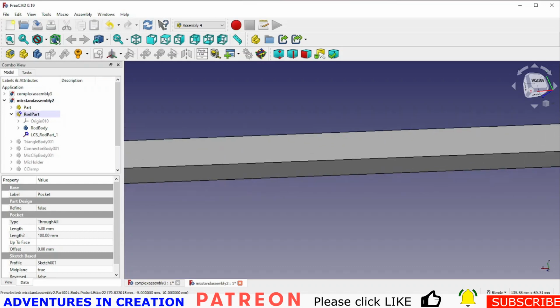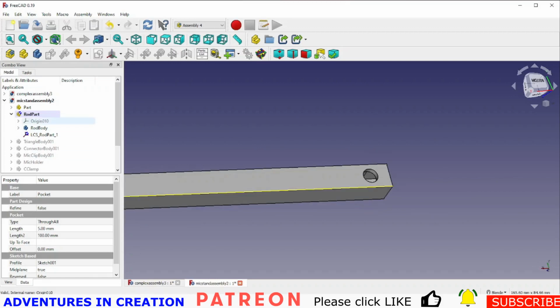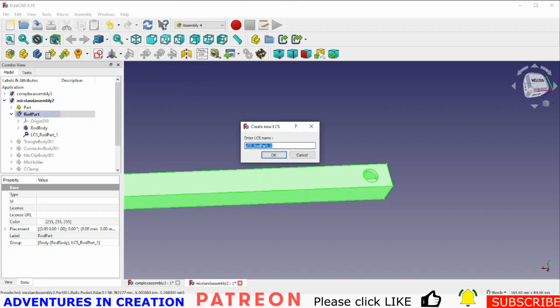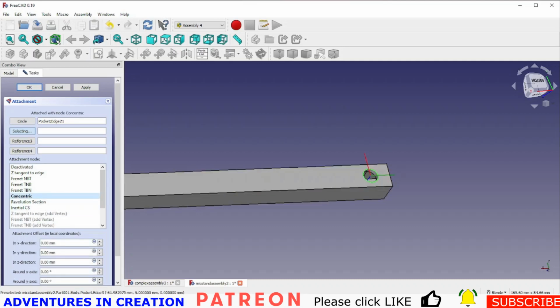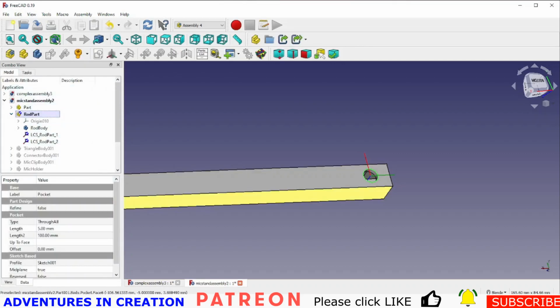And what I'm going to do is move to the other end of this rod, and I'm going to stay on this rod part, and create a new LCS. One thing to notice, when I click it, I'm selecting the whole part before I add these LCSs. It can be a bit finicky the way you add them. So this is LCS rod part 2. I'm going to say OK. Pick that concentric circle on this hole. I'm going to say it's concentric. There's my LCS. Say apply. Say OK. Now that part is ready to be assembled into the assembly.